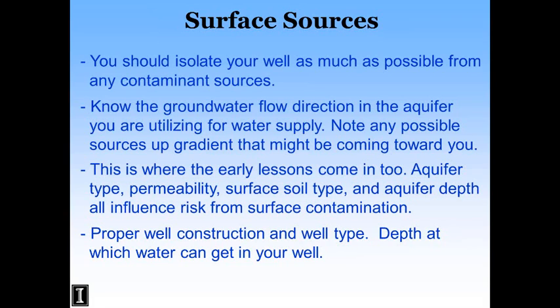Proper well construction, again, shallow dug wells, and again, these webinars are kind of a snapshot of what's in our class materials, and it's covered in much more detail. And so if you aren't taking the class, you really need to have those materials for a resource to really get a better feel for what kind of things you can do and how you might protect your well. But proper well construction, again, if you talk about old hand dug wells or wells in a pit, things where you're risking very shallow infiltration into your well is much more of a risk than if your well's coming from a very deep aquifer, maybe several hundred feet under the ground.